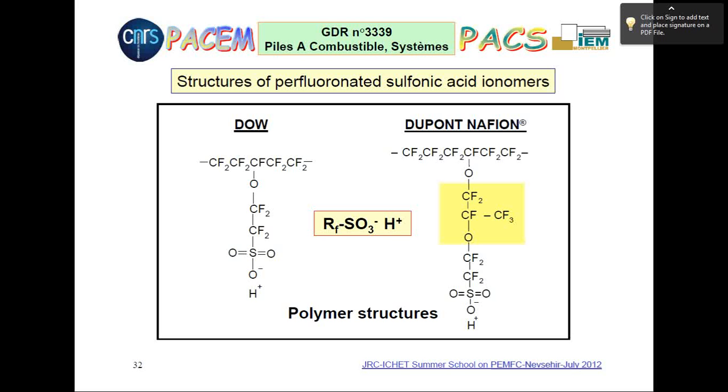Just a simple idea: the proton usually is solvated by water. It's a very strong solvation process. So you need water to have a free proton. It means that you have to humidify the membrane. So in the system, you have a humidifier because of that.